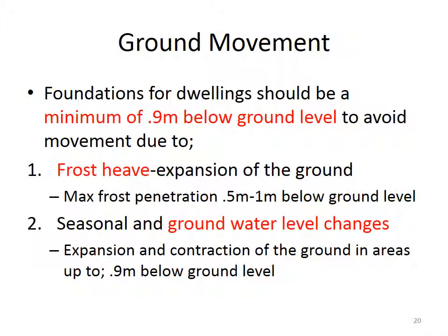during the winter, obviously the water table is going to rise up. During the summer, it's going to drop down. So it would be important, like if you put in a foundation and you went down too shallow, and it was maybe during the winter time or autumn time or whatever, and everything was fine, but then during the summer, if it dried out excessively, the ground could shrink and your foundation could break.